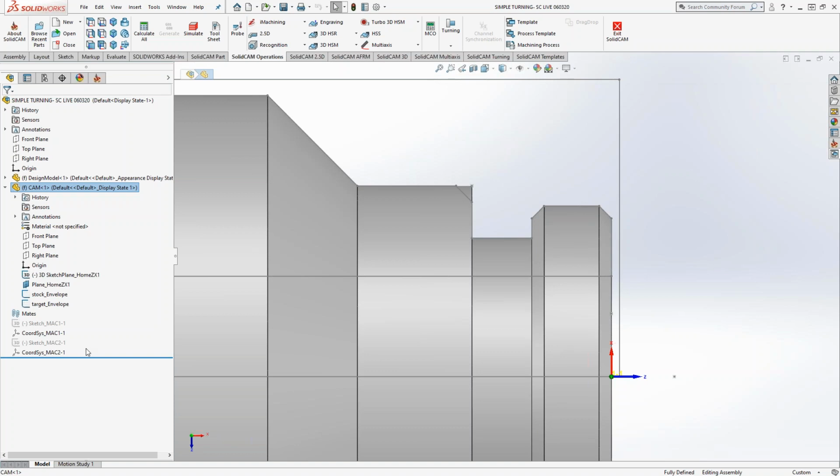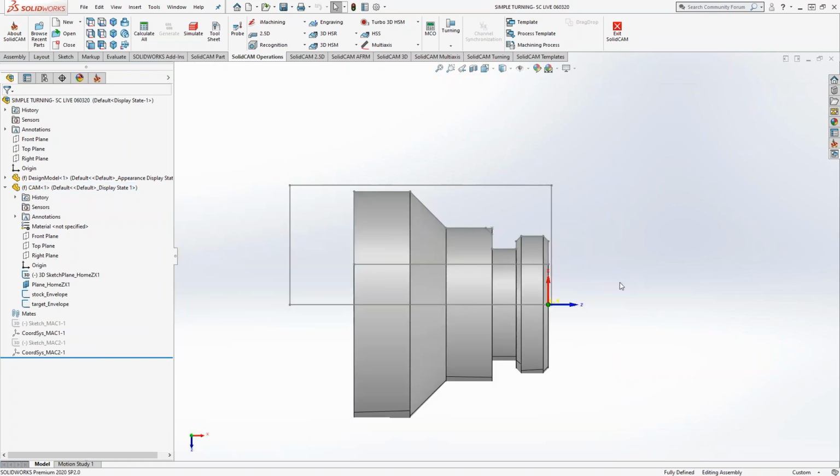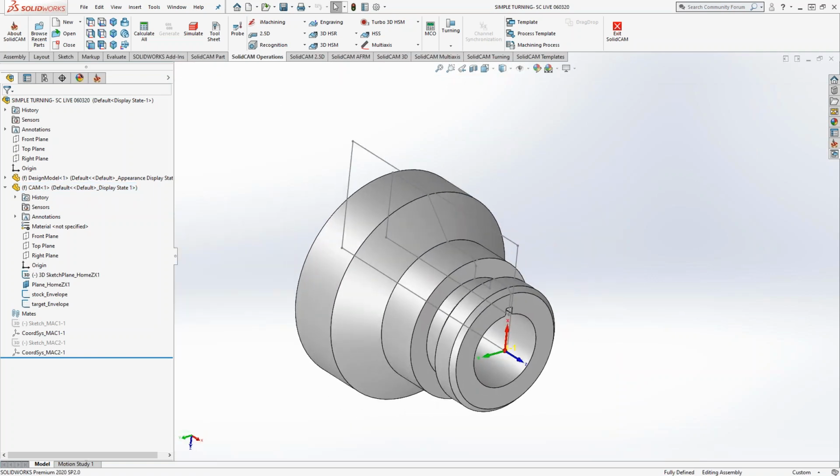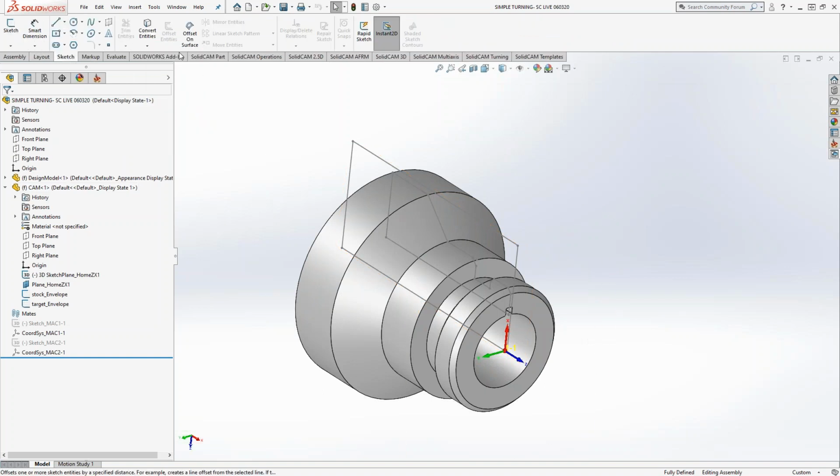But I have found that if you try and do a sketch on an assembly level, you don't have as much access to some certain geometries that you do when you go inside of a part file. Well, if I go to sketch here, I think this is a perfect example. I don't really get the ability to do offsets. You won't really sometimes be able to do convert entities, because on the assembly level, there's no specific solid that you're looking at. So it's kind of more of a SolidWorks question: when do you do sketching at an assembly level versus when you do it on a part level? That's really the difference. This is a part level sketch and this is an assembly level sketch.